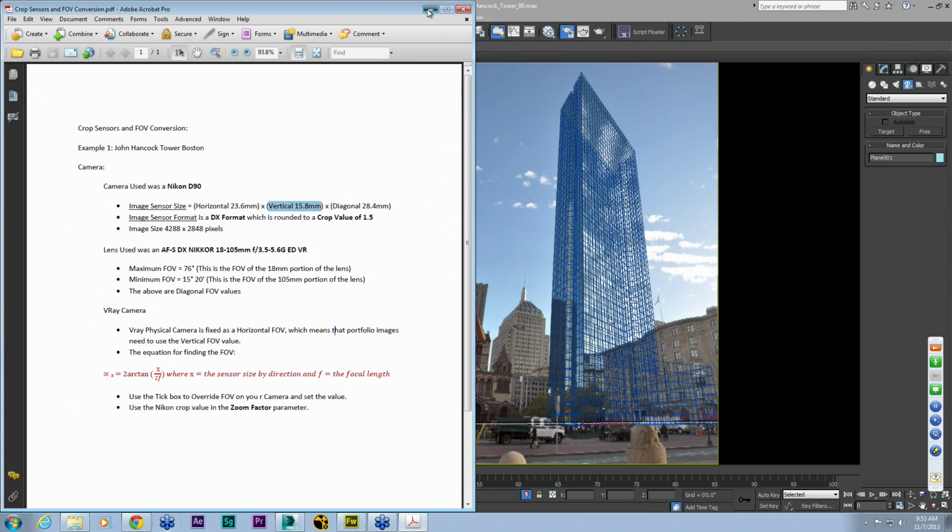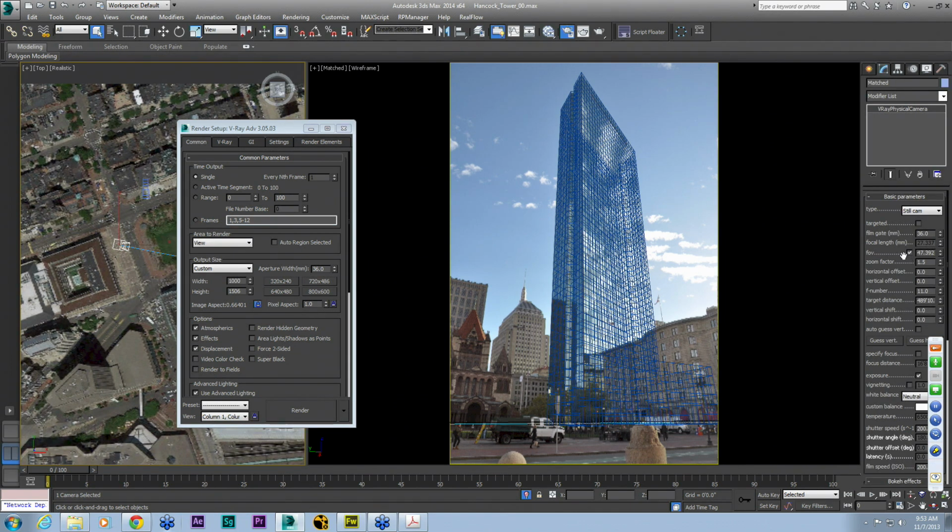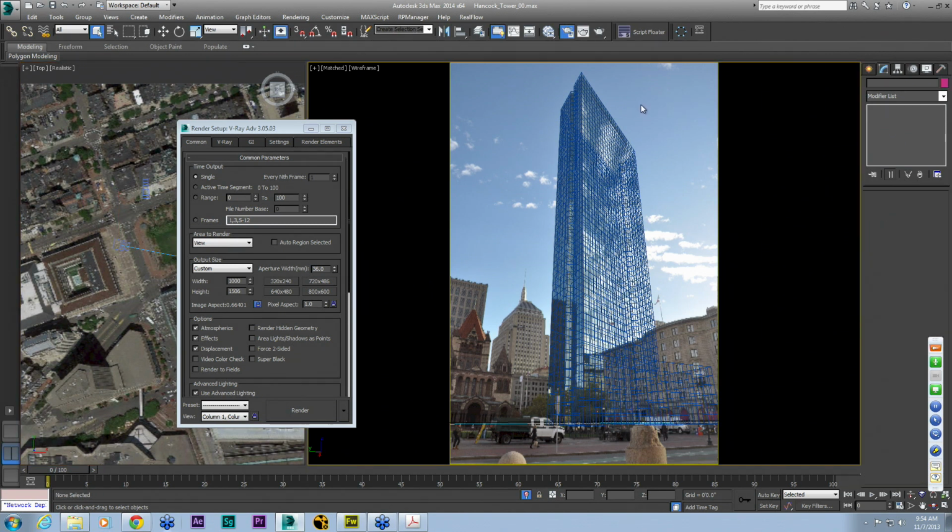And so, as I said, when you're in the V-Ray camera, tick on field of view and override it with 47.392. You could have also just multiplied by 1.5, but I haven't really done a broad range of focal lengths on this to feel confident about just that simple math of 1.5 on the focal length. I feel it was more coincidental in this case. So doing the field of view is going to get you a lot more specific number. And then as you can see with the match here, it was near perfect with the geometry that I had in the scene.